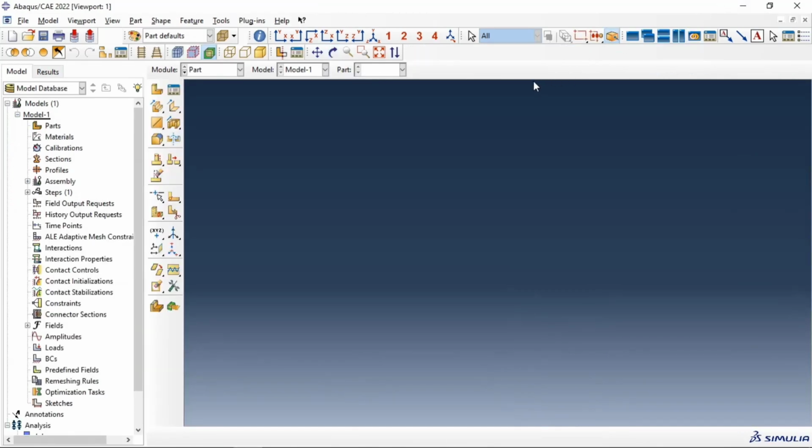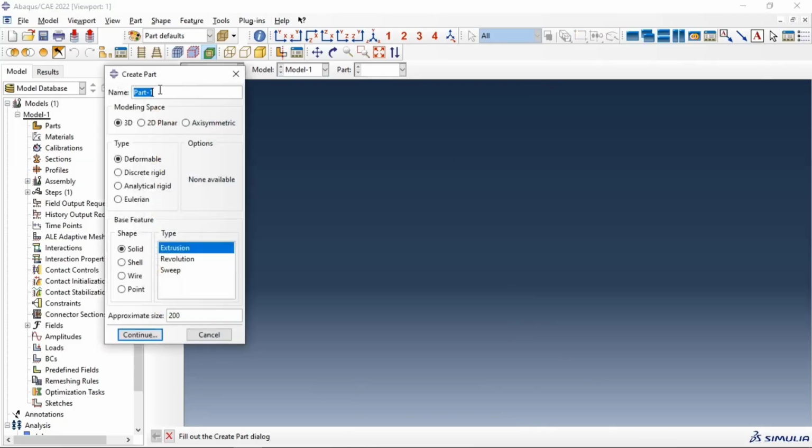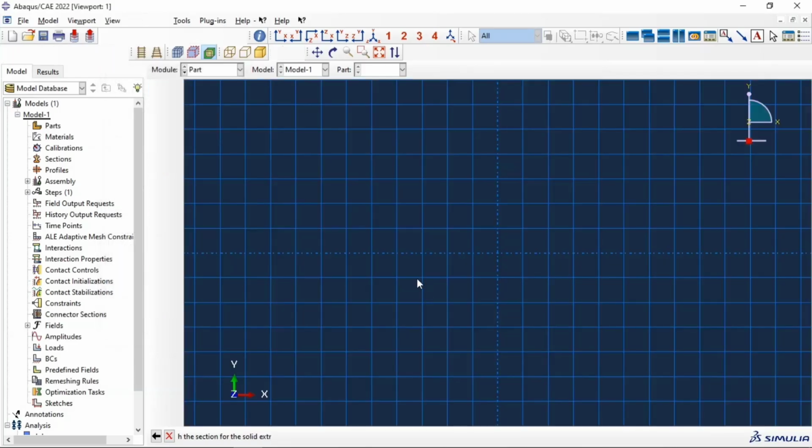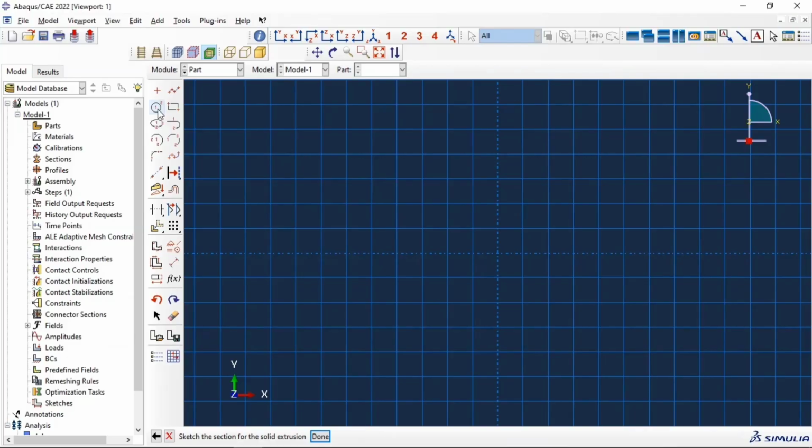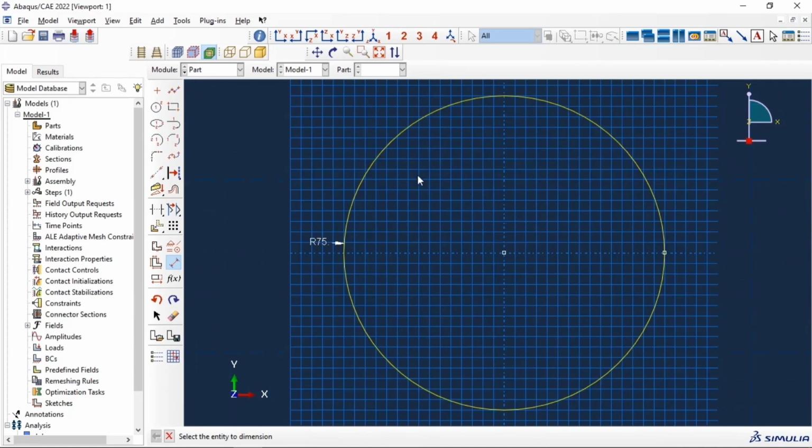The concrete damage plasticity model is specifically developed to capture concrete crushing in compression, cracking in tension, and stiffness degradation during loading. So, by the end of this analysis, we'll have created a concrete cylinder geometry, assigned the concrete material property, and applied the load and boundary conditions. We'll be creating a specific mesh for this model. We will configure the nonlinear analysis details. We'll monitor convergence using scaling, and we'll check the results after the analysis gets solved.